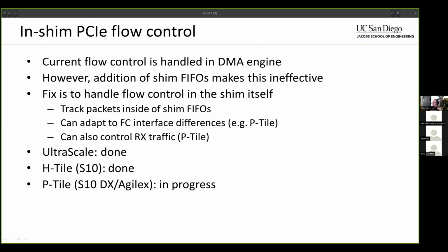So you've got to jump through some additional hoops in order to do the accounting properly, because you can't see what credits the core is consuming, but you do see the credits that the core consumed getting released. So if you don't do something, then those numbers are going to diverge to a point where you're going to think you don't have enough credit, and then it'll hang.